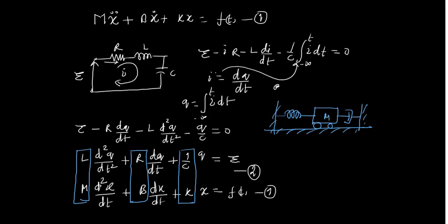Okay, this is m, this is k, this is b, and we have written these equations. So these two are analogous to each other, and this is what? Force voltage analogy. So can we say that this system can be drawn equivalently as an RLC circuit. This is basically like a suspension system. You remember that? You have already studied it in mechanical.